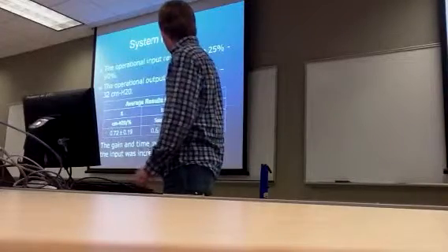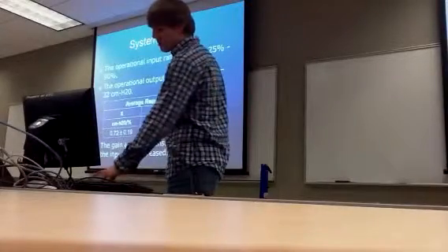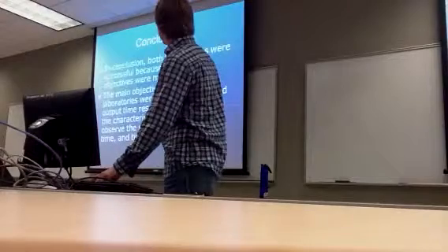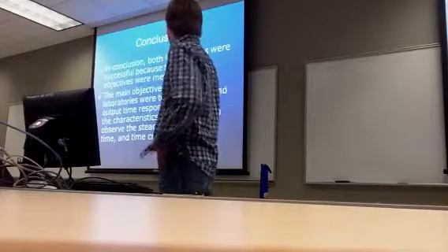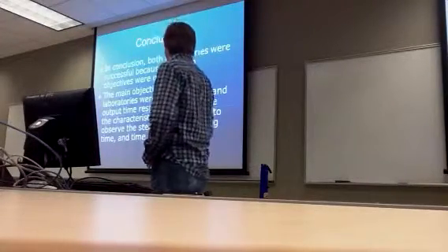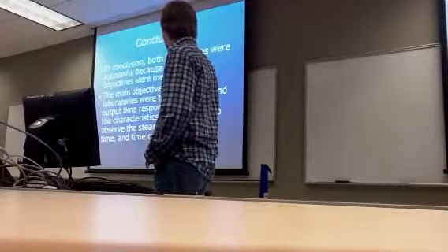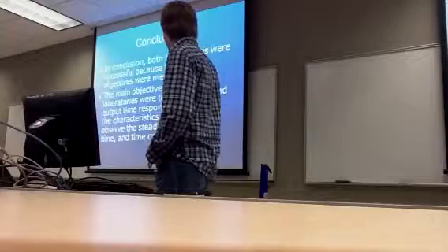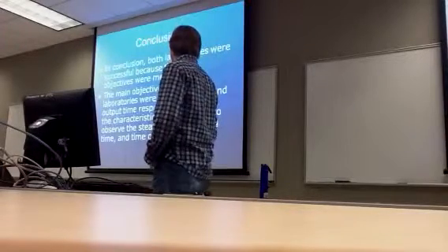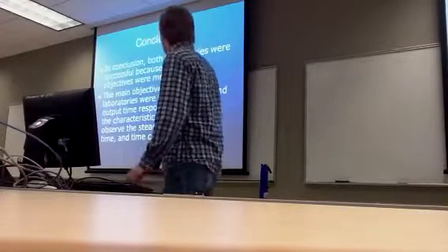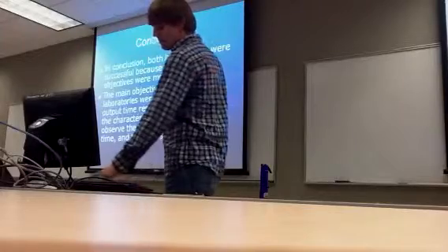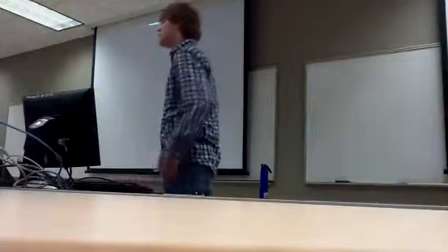The gain and time constant both increased as the input was increased. In conclusion, all the objectives of the lab were met. We studied the input and output time responses. We determined the characteristics of our steady state operating curve, and we observed the steady state gain, lag time, and time constant. Are there any questions?